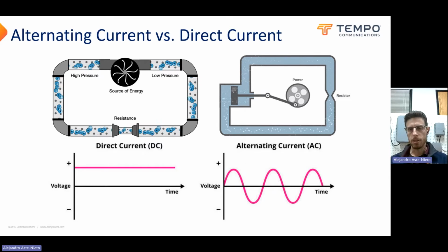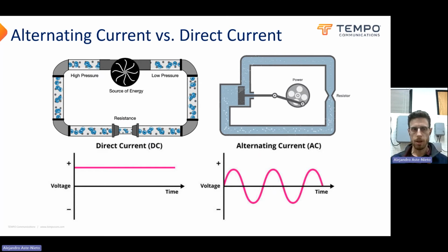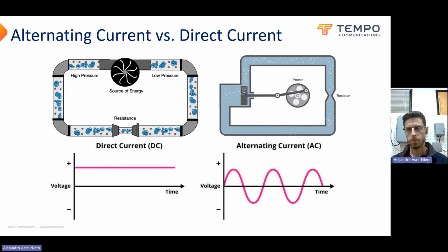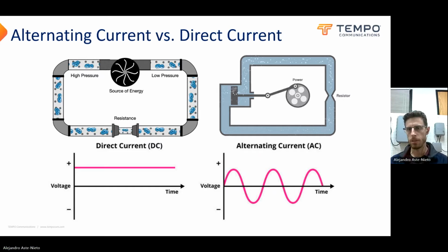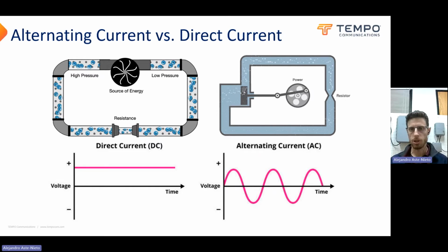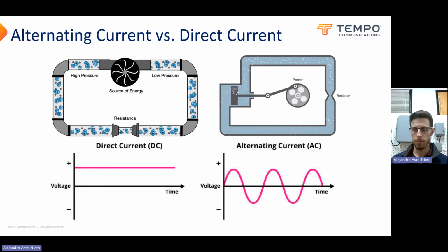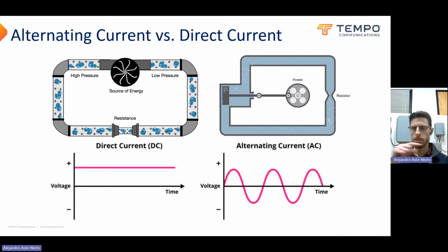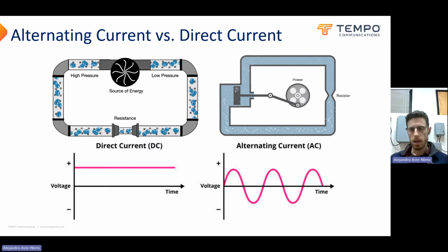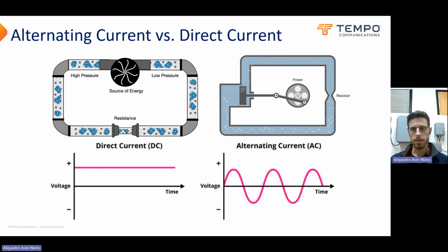And the reason for that is because you can take a certain amount of AC and transform it to a different voltage without much energy being lost. In fact, when you plug in a controller, a lot of times it's taking 120 volts of AC and turning it into 24 volts going to your solenoids through the transformer inside the controller. So DC we tend to use in batteries and sensitive electronics, things like digital computers, phones, things like that.